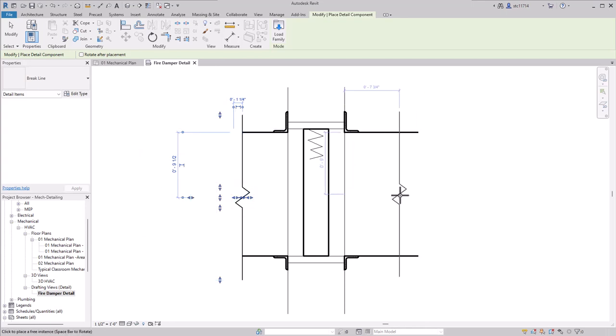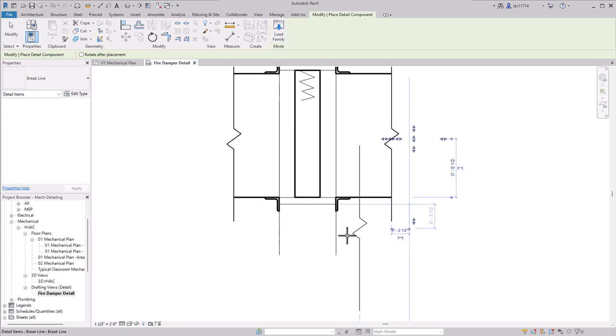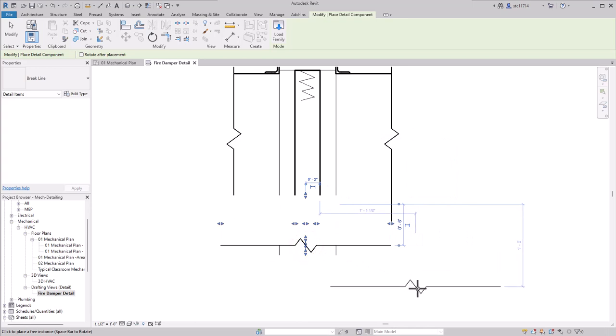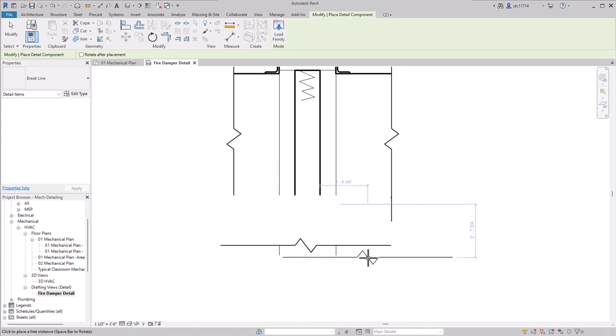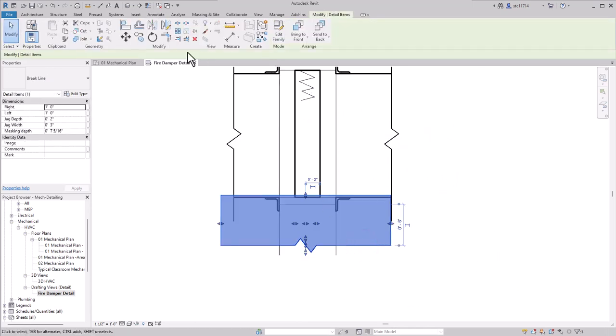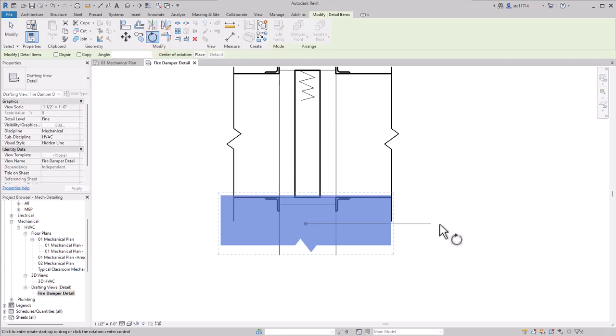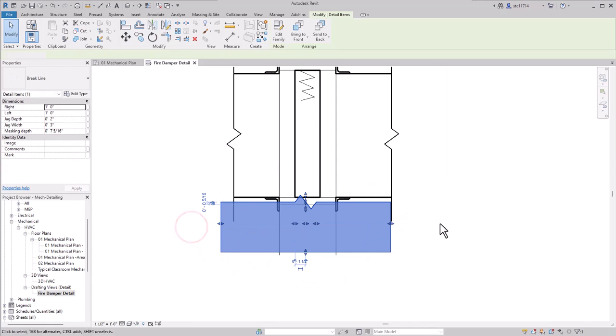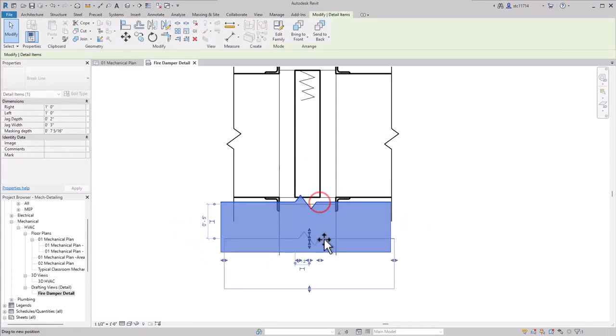So on the other side, I'm going to tap the space bar to rotate it a couple times to wipe out what's to the right. Then same thing here, I'm going to have it wipe out what is below. Now if you click and you accidentally put it in the wrong direction, not a big deal, I can just rotate it afterwards. So I'll use my rotate command, rotate it 180, and then I can move it into place as needed.